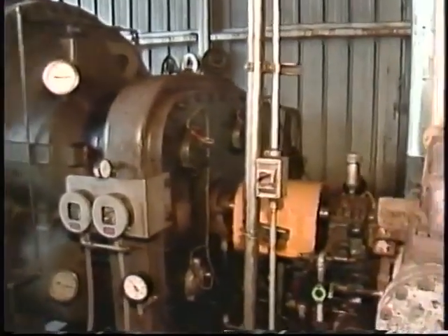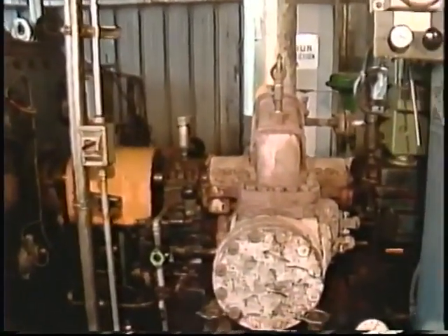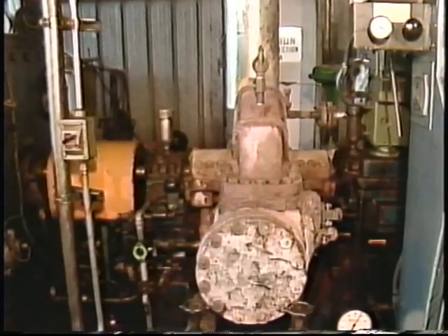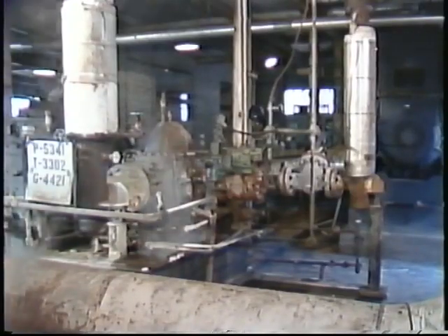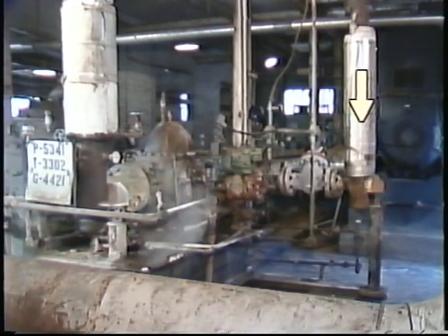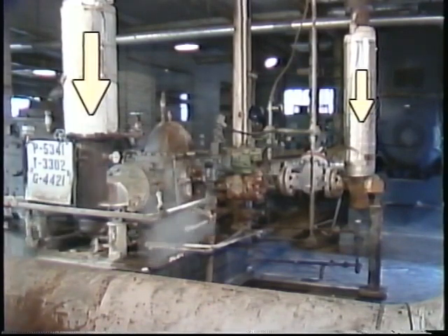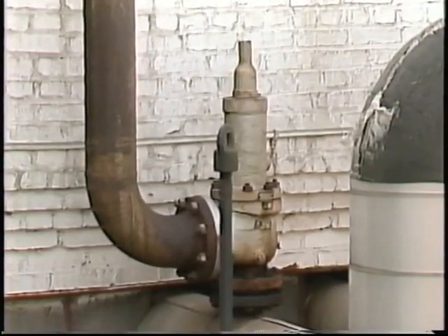In other cases, the speed of the turbine may be steady, but too fast or too slow. The turbine may run too slowly if the inlet steam pressure is too low, or if the back pressure is too high, which can cause the safety relief valve to open. It's possible, too, that there simply isn't enough steam available to provide the steam pressure needed, or the turbine's overspeed trip valve isn't opening fully.